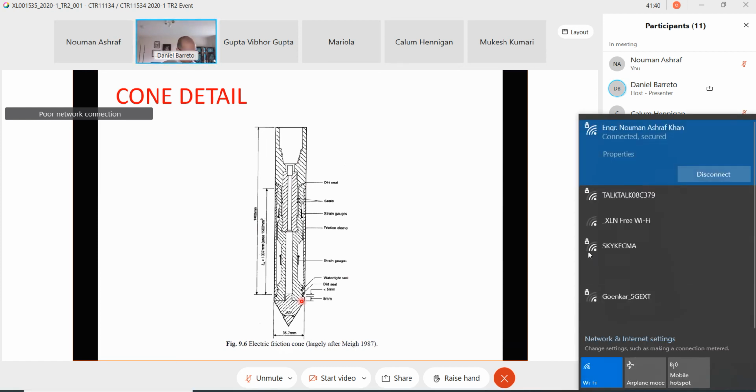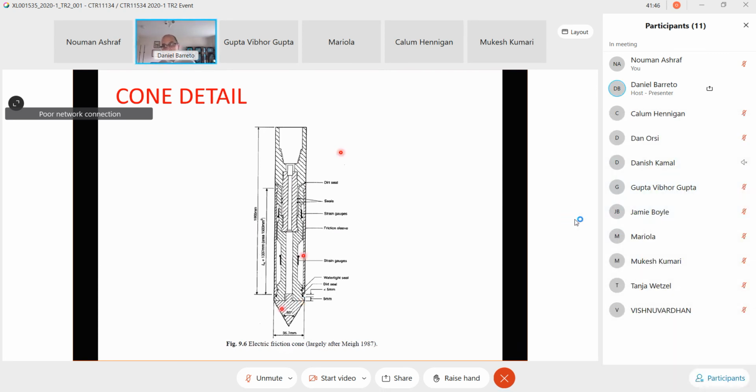And those things that we have much more experience with are, in particular, the CPT test, which is essentially a tube with a conical tip that I'm showing here in section. And the idea of the test is that as you penetrate it into the ground from your vessel, also charging you per time, you can measure the tip resistance, but also the distance. Quite similar to how your pile capacity is related to the tip resistance, you also measure shaft capacity related to the sleeve resistance on the sides.